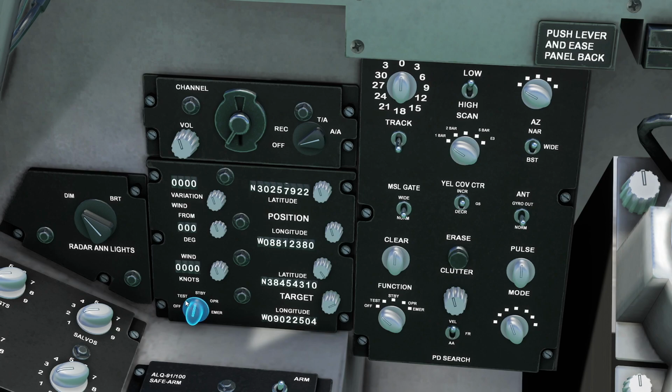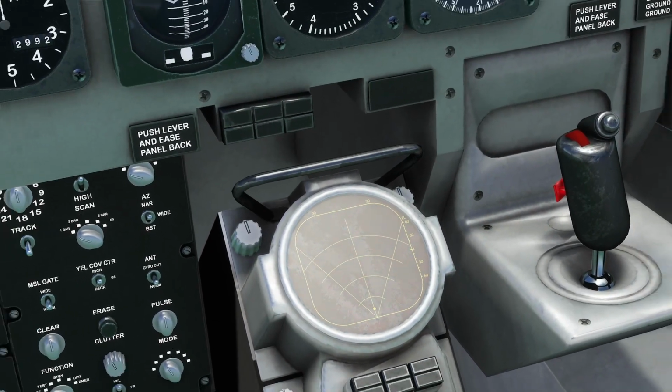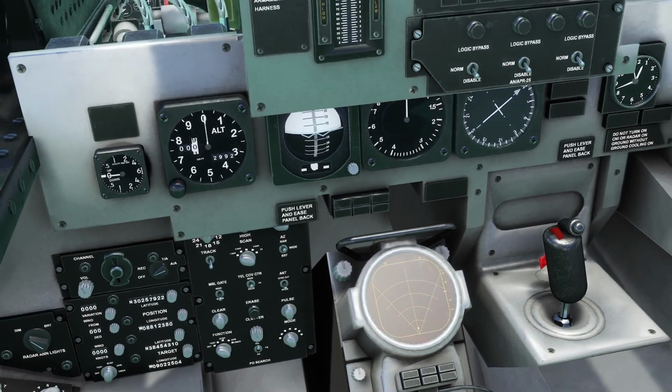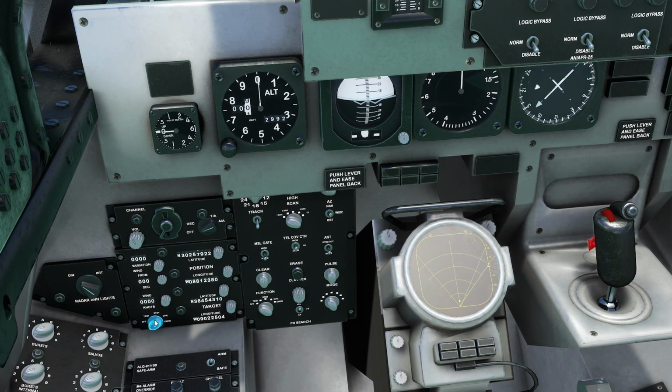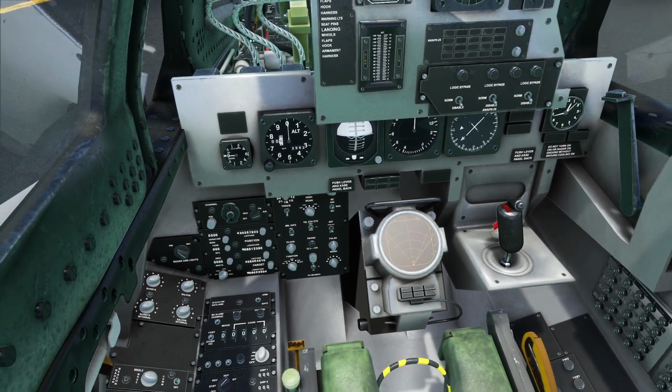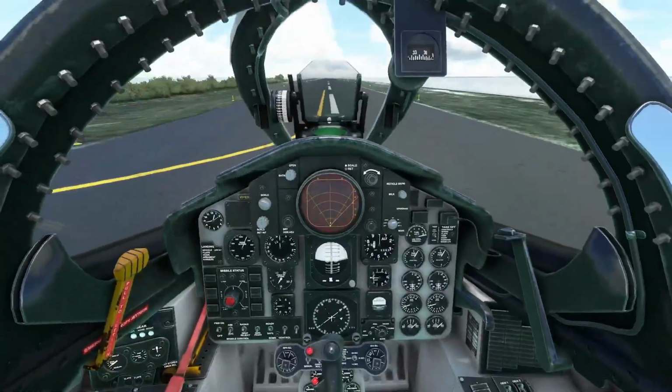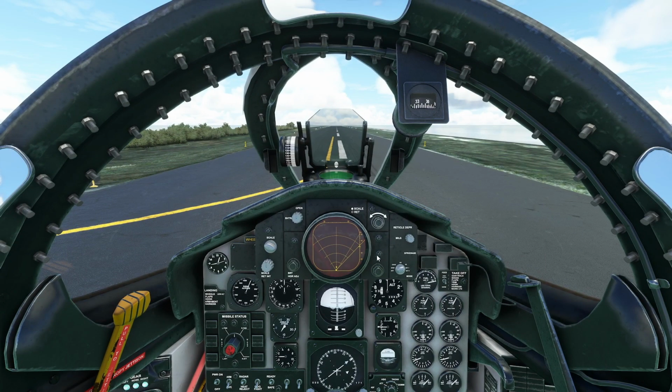So like I said, you want to key that in standby mode. I did not have it in standby mode, but I believe it's still going to work. As long as you're not in operations, I believe it's going to work. So once you have that keyed in, move this into OPR, to operation. Yes, it did. So boom, you just saw that flight plan just appear right there. So let's go back up here. And we see it right there on our screen from where we are to where we are headed. There is our line.